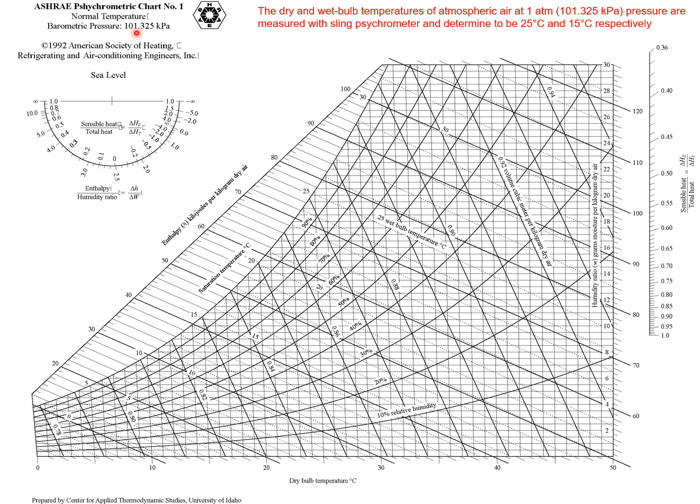Now let's start. We have the dry bulb temperature 25 degrees C. You can see here, this is the axis for the dry bulb temperature. You need to find where 25 degrees C is. We have 20 degrees C here and 30 degrees C here. Obviously 25 degrees C is somewhere in between. So you need to draw a line at 25 degrees C to represent this value. This is the line that I've drawn to represent 25 degrees C.